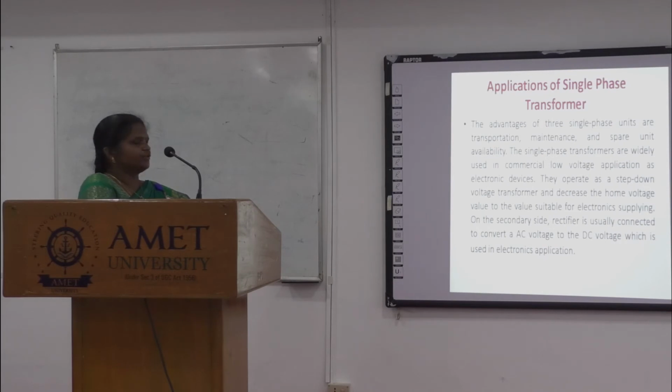Coming to the application of single phase transformers, the transformers are used everywhere wherever the voltage needs to be stepped up or stepped down, and in most of the applications, everywhere from generating station, distribution and transmission, these transformers are used. The advantages of three single phase units are transportation, maintenance and a spare unit available.